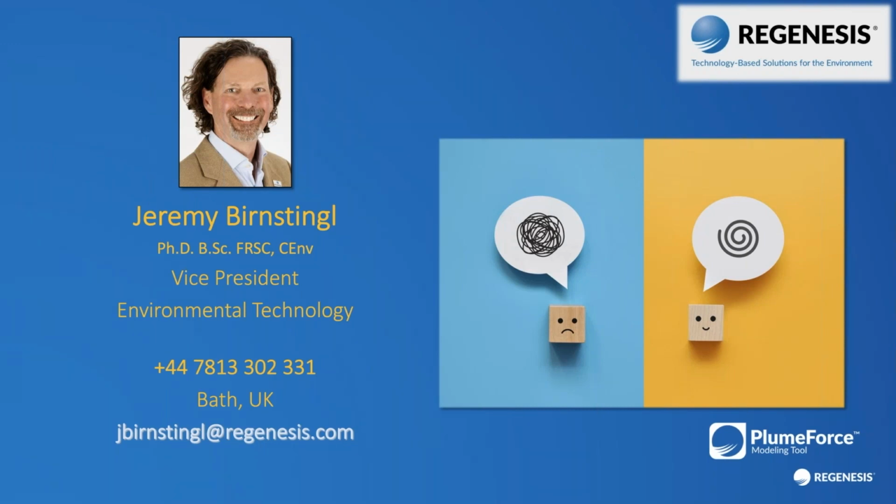All right, thank you, Jeremy. So here's another question, and the question is, how do you calculate the KD to put into another model? Okay, that was buried in the webinar early on. Basically, you need to know the isotherm of the species that you're dealing with, and KD is the ratio of sorbed mass to dissolved mass at a given equilibrium concentration, then corrected for the amount of PlumeStop in the system, the FCAC that we've applied. In other words, the y-axis divided by the x value.